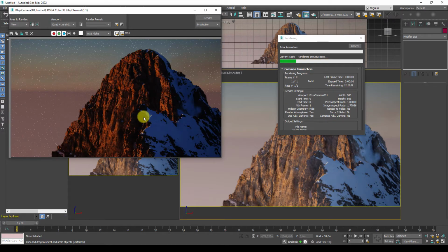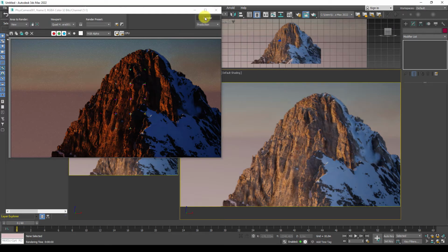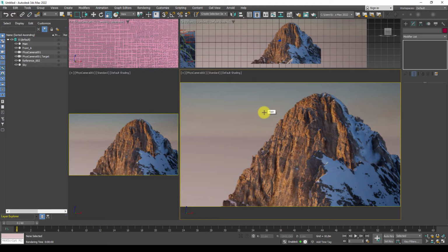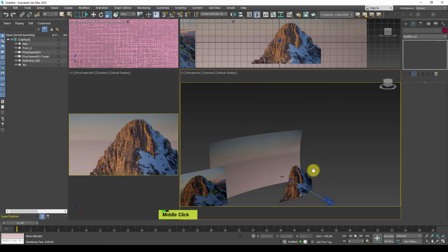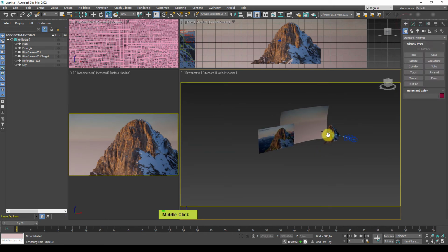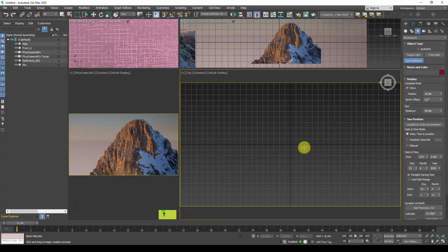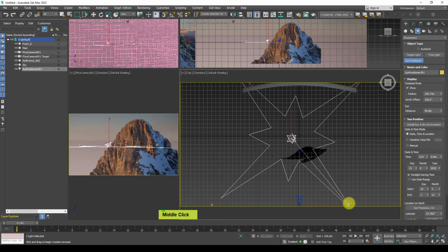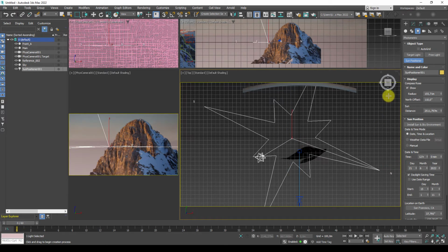So we have a backdrop, everything is visible, it's totally dark, so we definitely have to use a light source. Now, if you have a concept art, you definitely have to take care of the lights. Now, this one is an existing image, so the light is there. We have to conform to the existing lighting. Okay, so in the light sources, we can use photometric sun position or type of light, top viewport, Z zoom in, and drag it out and lift this up, rotation and lift this up, make sure it's going pretty high.